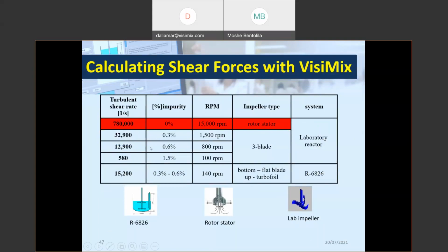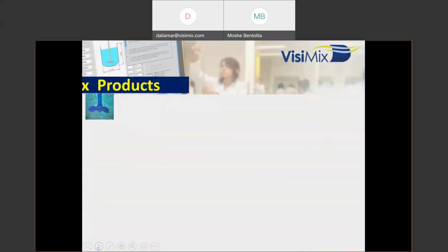So you will always have impurities at this level. But when you increase the shear rate and the diffusivity, even if local, you get zero impurities. And the solution was to install this rotor-stator close to the feeding position. So the feed enters the rotor-stator, reacts because it's a fast reaction, and releases a product with even close to zero impurities. Okay, so this is very interesting.